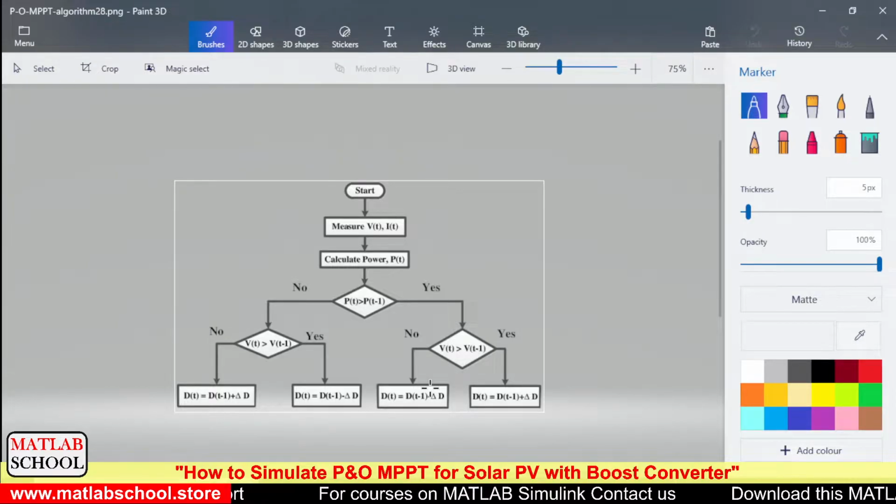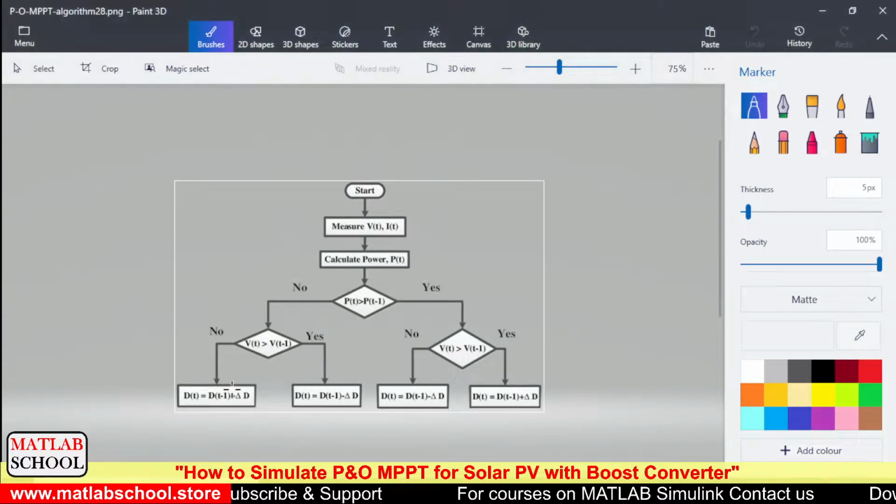the pulse width. On the other side, if the current power is less than the previous power, again we will be comparing the current voltage with the previous voltage, and if the current voltage is found to be greater than the previous voltage, we will be decrementing the pulse width. And if the current voltage is found to be less than the previous voltage, we will be incrementing the pulse width. So del D is the small change in pulse width. Based on that, we will be implementing the MPPT.